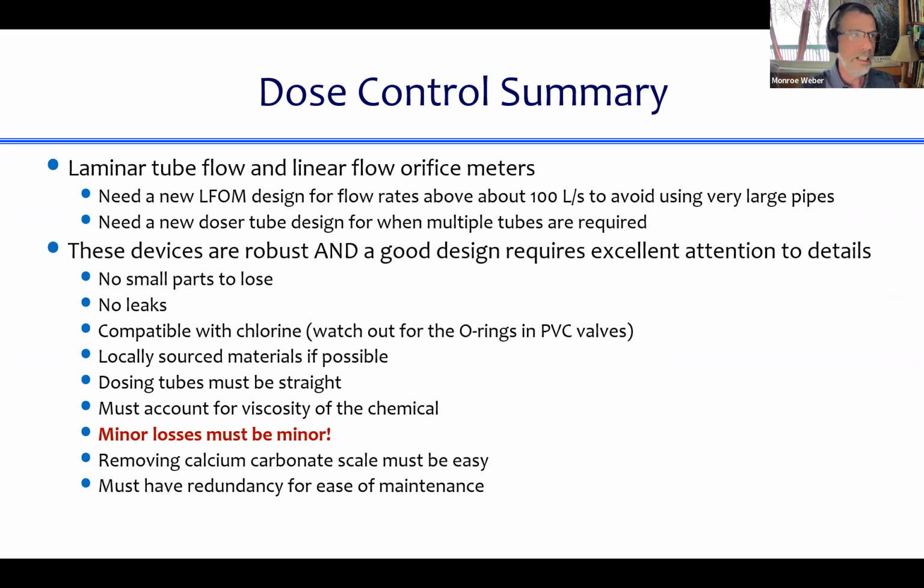And if you think about the idea of the LFOM, it was that it was just shoved into a coupling that was buried in the concrete in your entrance tank, like the one that you designed. And the idea was that you could actually take that LFOM out of the tank if you wanted to. Once you go to a larger plant, that's not going to be possible because a human cannot lift a 2-foot diameter PVC pipe out of a coupling. It's going to be in there too tightly, and you just can't do it. And the 2-foot diameter, 24-inch, 60-centimeter diameter pipe is also quite expensive.